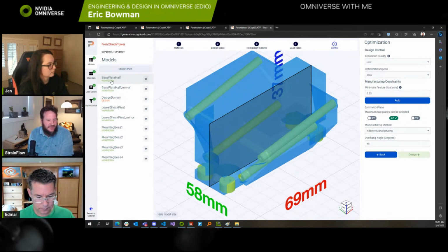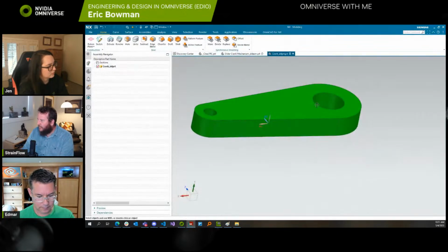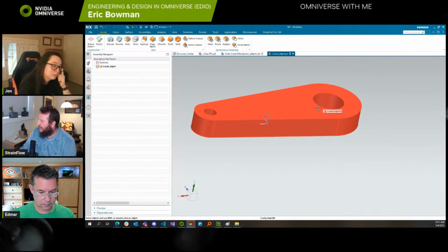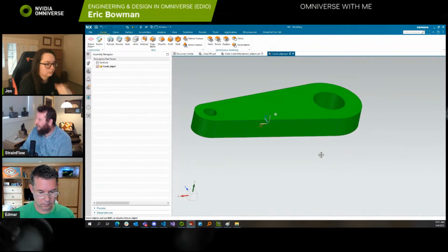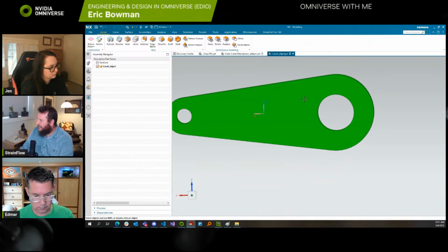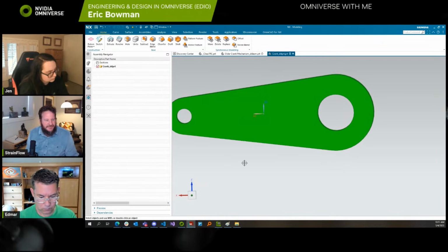It'll whittle those joints down to nothing. So if you look at this, we have a bolt through here. You've got to have some material all the way around that bolt. Otherwise, the design is not going to actually work. So we'll just draw a little cylinder around this, and a little cylinder around this. Those represent some space that absolutely must be there at the end of the design.